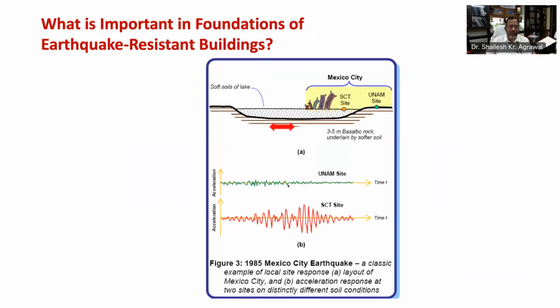Let's conclude it now. Amplification of ground motion depends on soil properties, which comprises of its shear modulus, damping, soil layers and layer properties, saturated versus dry soil, loose versus dense soil. It also depends on ground motion characteristics. In general, stiff soils have lower amplification while soft soils higher. Seismic design codes provide response design spectra for underlying soil strata for different soil types.